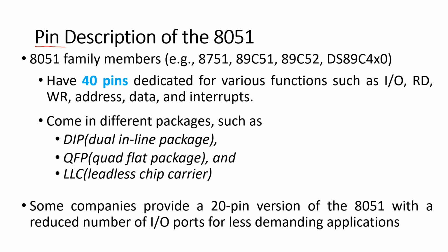Now, in connection with the pin description of 8051, 8051 family members can be many. To be specific, there are a lot of examples of 8051 family members: 8751, 89C51, 89C52, 8031, and many more. The 8051 has 40 pins dedicated for various functions such as input output, read and write, address and data, and also the interrupts.